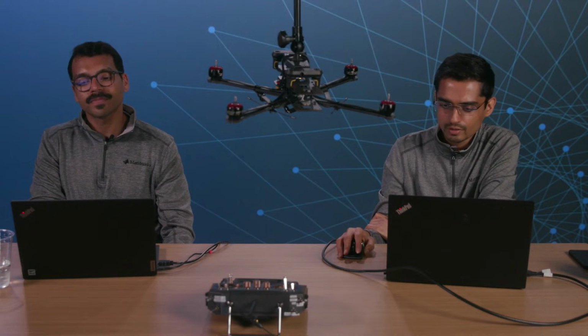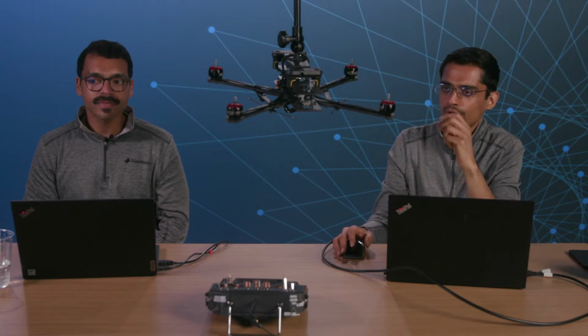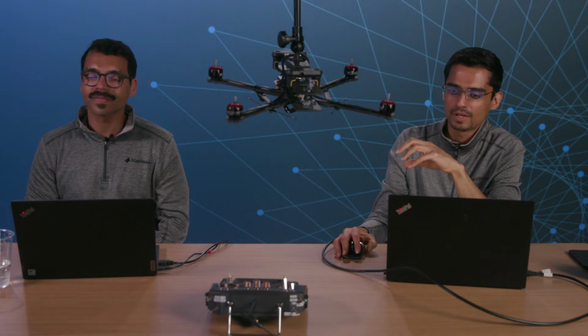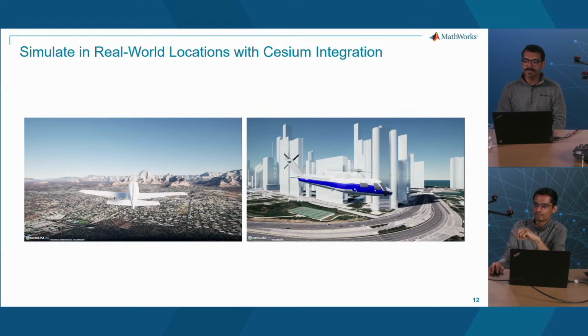There is a quick question on how to connect Unreal Engine with Simulink. So the way that Ronald showed to bring those boxes, that's it. Unreal integration is basically bringing in those Simulink blocks and doing those quick settings, and you don't need to download anything else other than Simulink and the required toolbox, which is Simulink 3D Animation, to build an Unreal scene.